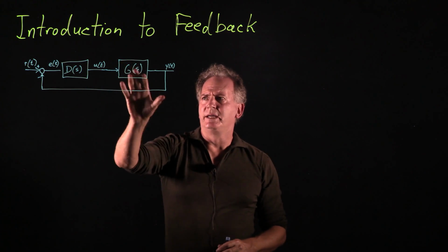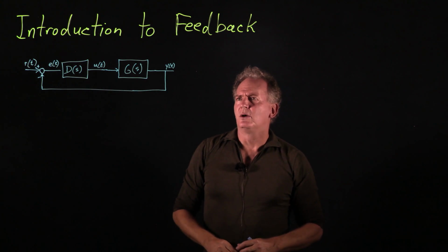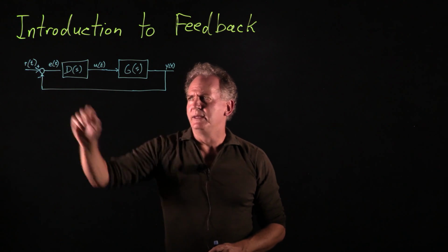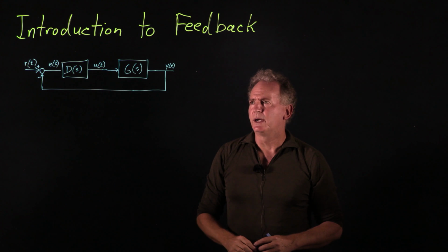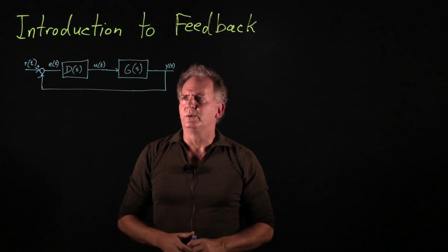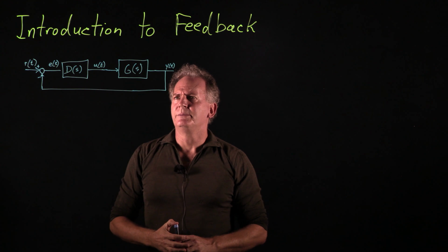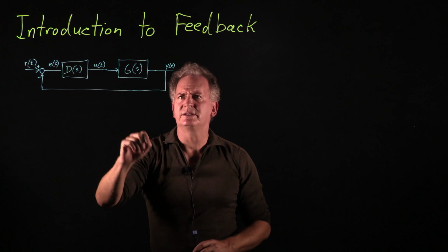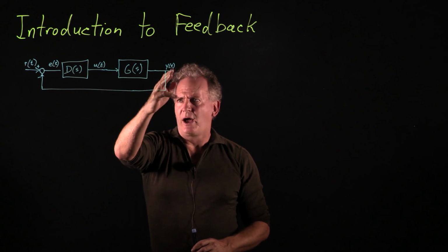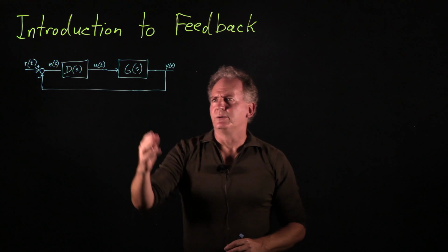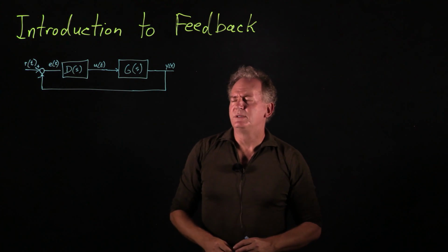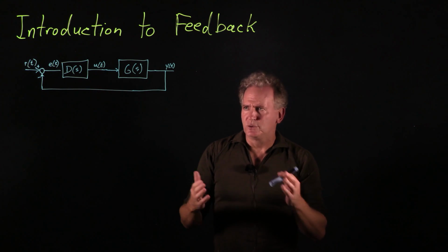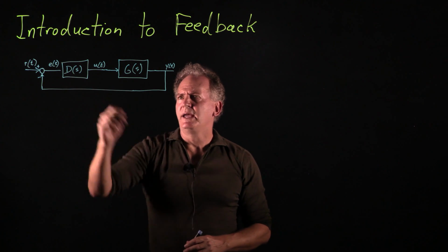When I write down my block diagrams like this, I'll write the signals in time above each wire, so you see the names of the signals that are going along those wires, as a voltage along the wire generally. And instead of writing the differential equation inside this box that relates the output to the input, I will simply write the symbol denoting the Laplace transform of that differential equation written in transfer function form. So G(s) here and D(s) here.